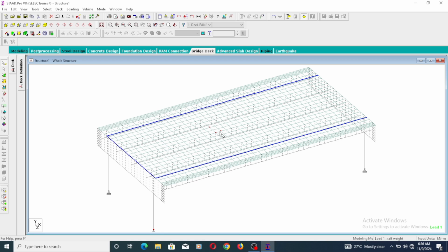So if I can obtain the local moment for the design, I will also select a suitable beam along my span, where I can obtain also the maximum moment for that beam. So I need to have a beam along the span, most likely close to the mid span, where I can obtain the maximum moment for that particular beam.